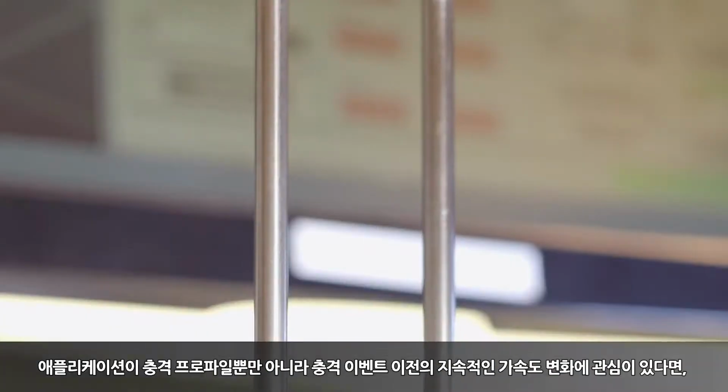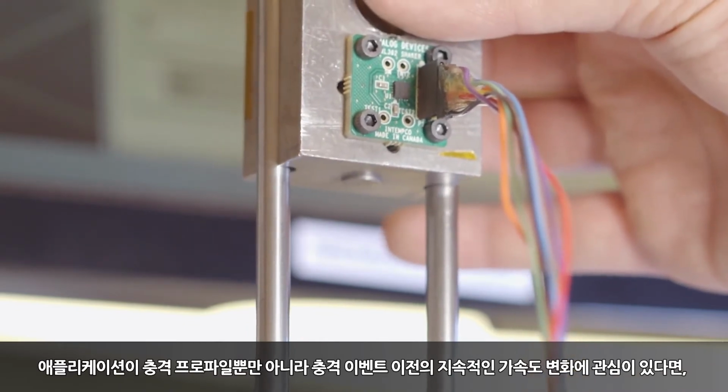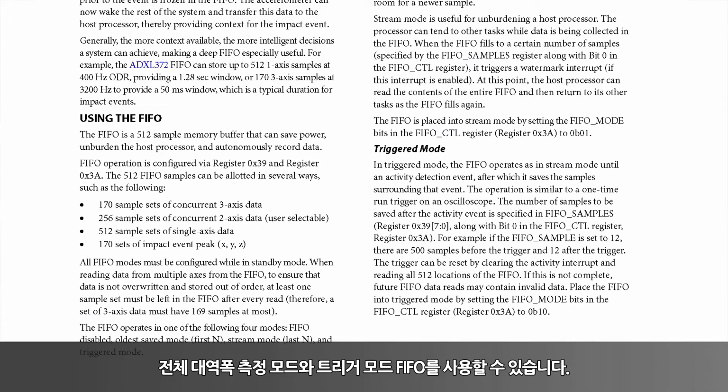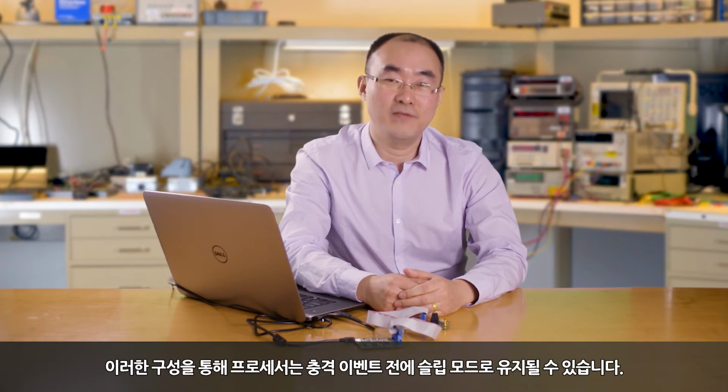When the application is interested not only in the impact profile, but also in the continuous acceleration change before the impact event, then full bandwidth measurement mode plus the trigger mode FIFO can be used. With such a configuration, the processor can be kept in sleep mode before the impact event.